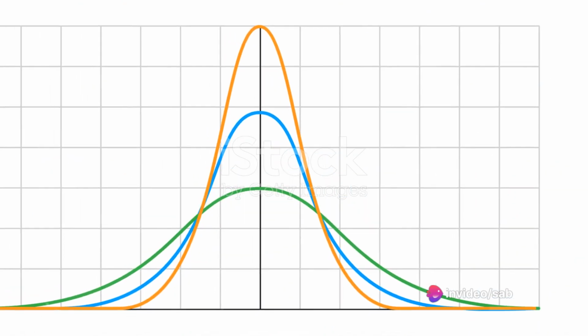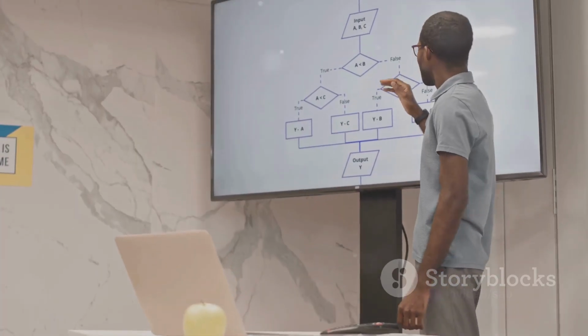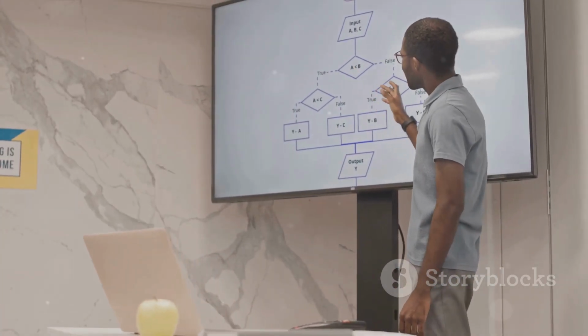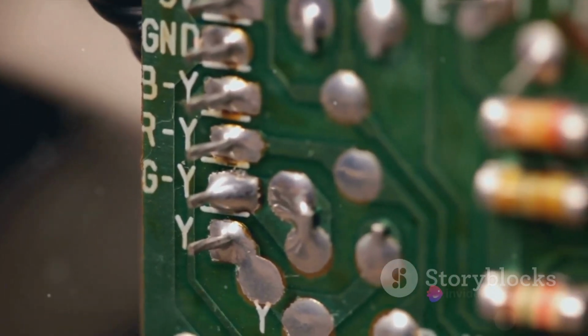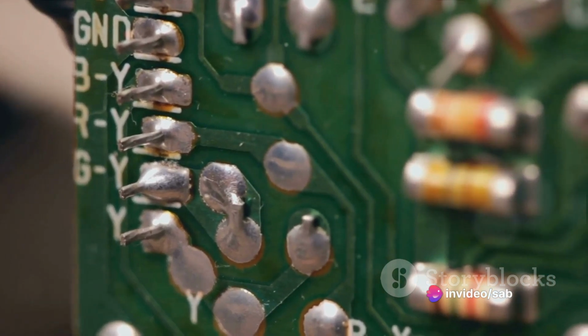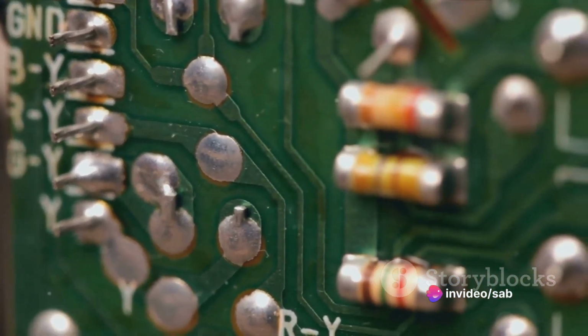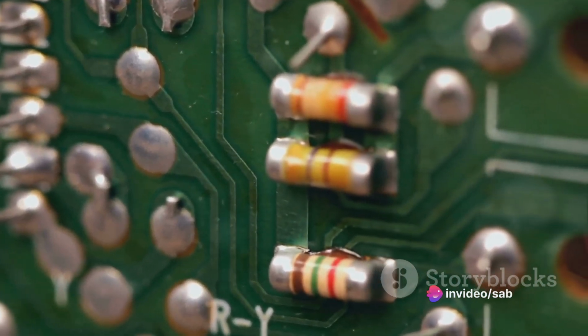The Smith chart operates on the principle of normalized impedance. This is a process where impedance values are scaled or normalized relative to a characteristic impedance. The characteristic impedance can be any value, but 50 or 75 ohms are typically used depending on the specific application.